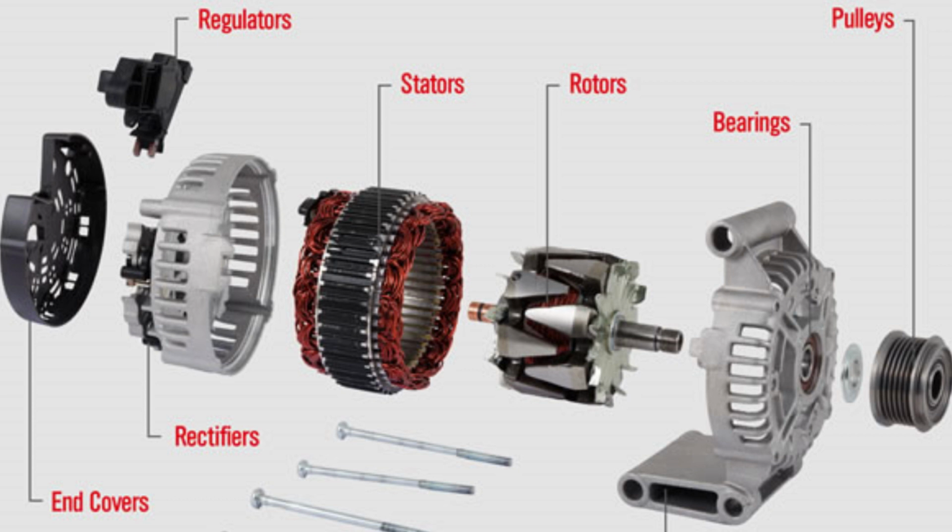Voltage regulator. The voltage regulator is a control device that regulates the output voltage of the alternator to ensure a consistent voltage supply to the electrical system. It monitors the electrical system voltage and adjusts the current supplied to the rotor windings to maintain a stable output voltage.